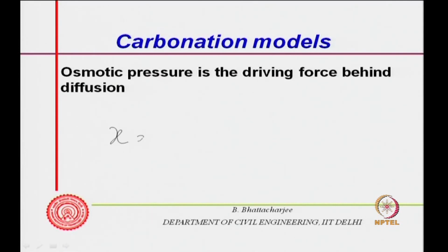If I call x the carbonation depth, this is important for us, right, and we do model this carbonation depth, because when the carbonation depth reaches the reinforcement level, that is the time depassivation can occur. So, therefore, service life with respect to carbonation will be defined when the carbonation depth has reached the rebar level or more. All right. Now, how does carbon dioxide come?